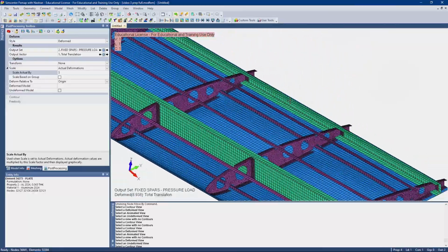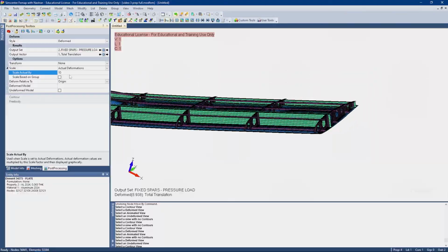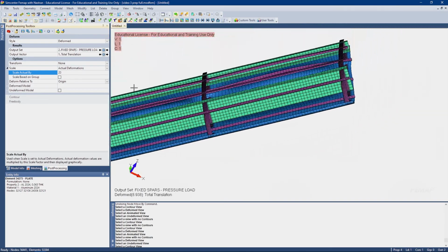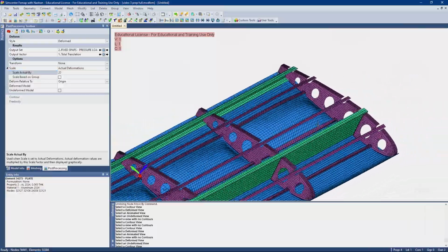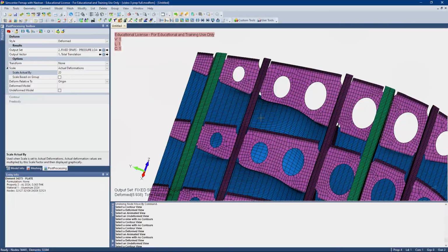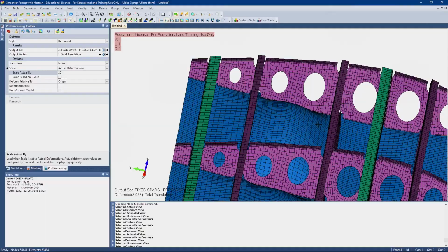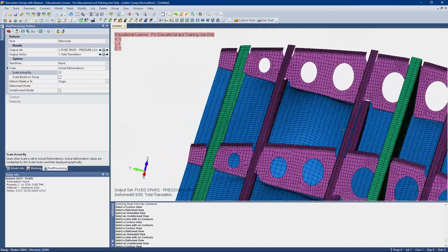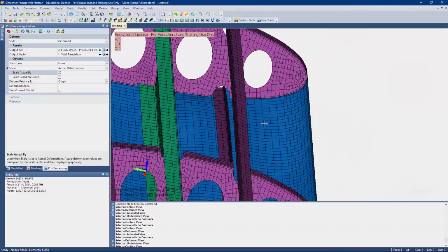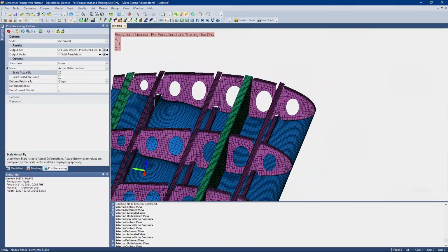And you can see that along the length of the beam here. Do a little bit more so it's very obvious. Let's try that. Yeah, here we go. So you can see that the skin's making a bubble kind of shape right here, and it's being held, constrained and stiffened by the stringers. And same thing here to a much less extent because the stringer is far closer. There's a bubble shape forming.